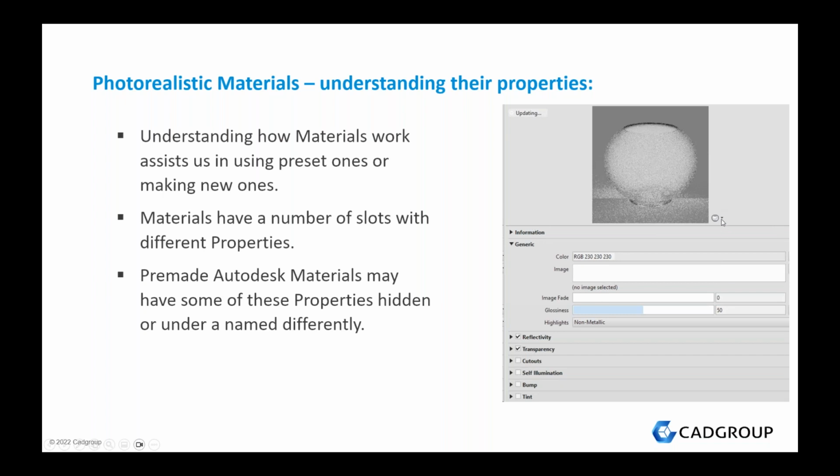You can control the quality of the preview, I guess, depending on your graphics card. You might set that to production or draft. If it's set to production, it takes a bit longer for the preview to update to look more accurate. But you can also change the preview. They call it the scene. So you can also change the object, the shape of it in the preview, which could be useful for different things. So if you've got a material that you're putting onto walls, then obviously having a preview of a wall material applied to a wall is a lot more useful.